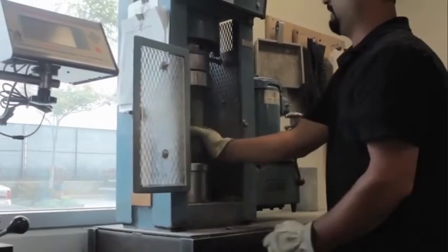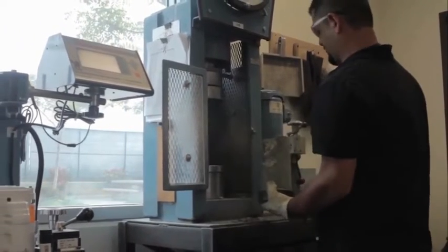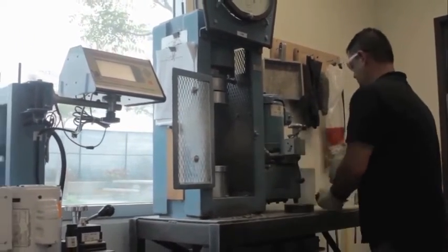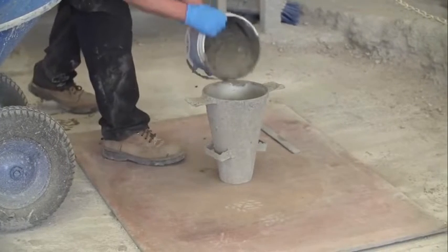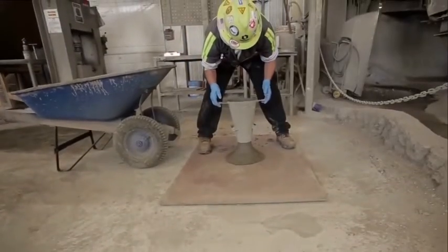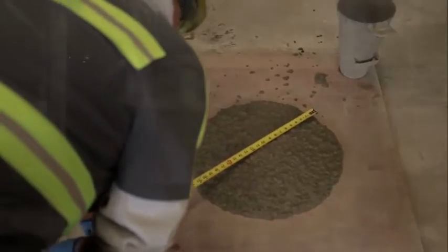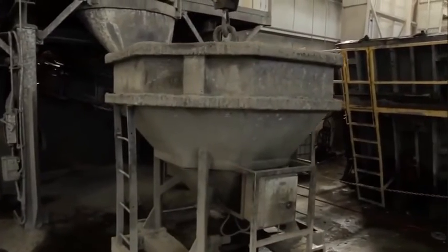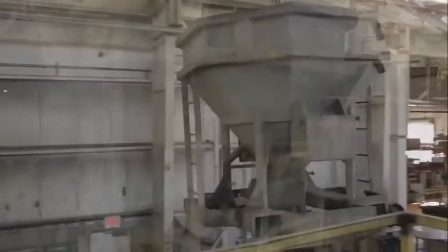The lab collects sample cylinders used to check compression strength and verify quality of each batch. Once the materials are properly mixed, the self-consolidating concrete undergoes a variety of additional tests, including a spread test to verify the mix has the proper flow and no segregation of the aggregate. The approved batch is transported in a bucket via an overhead crane to the product form on the production floor.